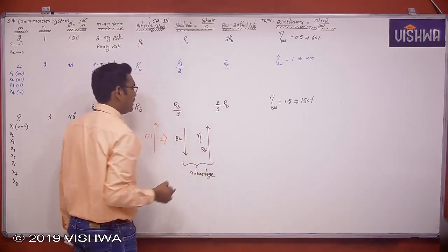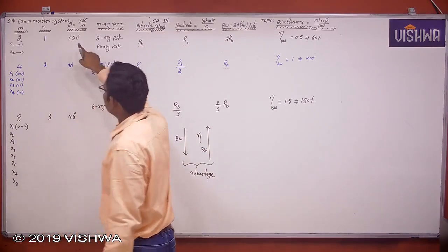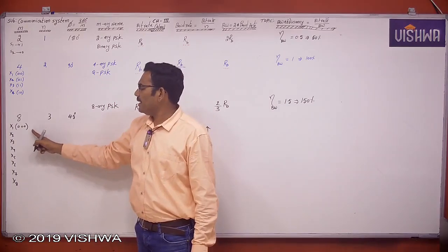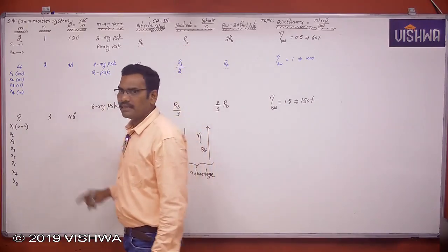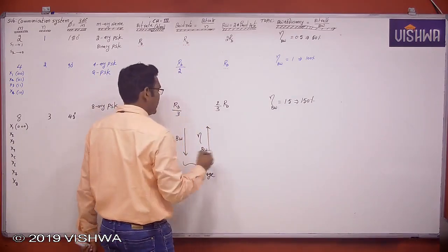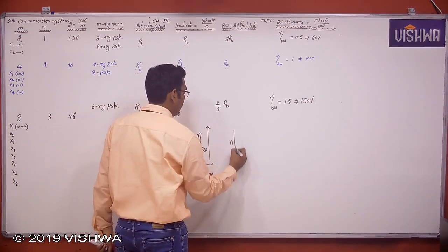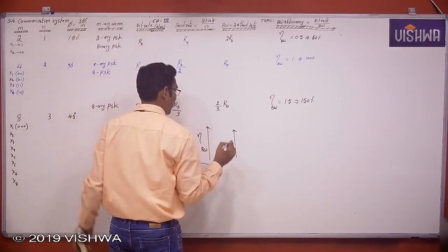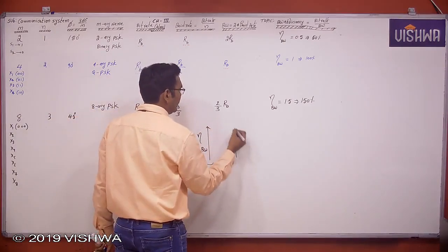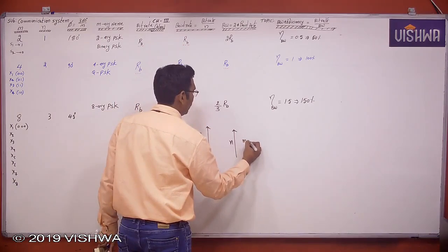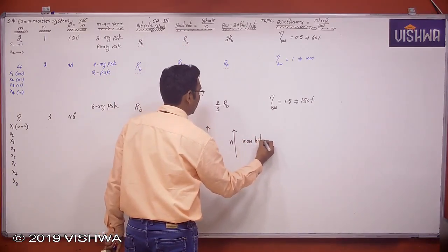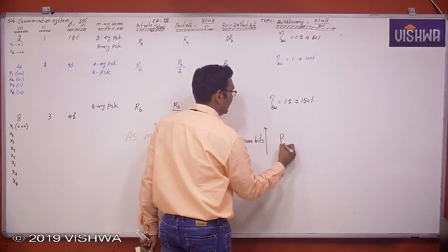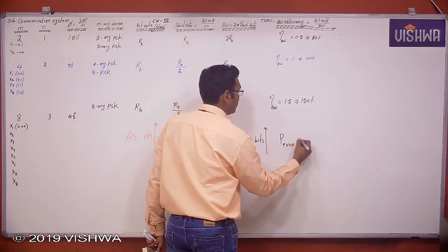But one disadvantage: as M-ary increases, the angular separation between the symbols decreases and the number of bits per symbol increases. As M increases, n increases. As n increases, more bits means probability of error is also more.